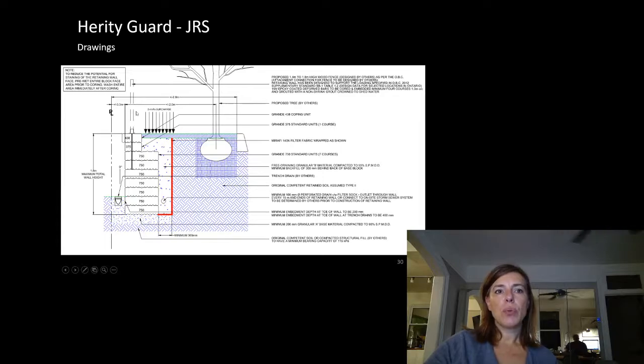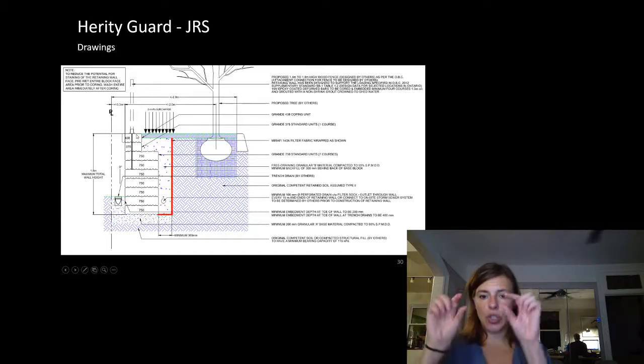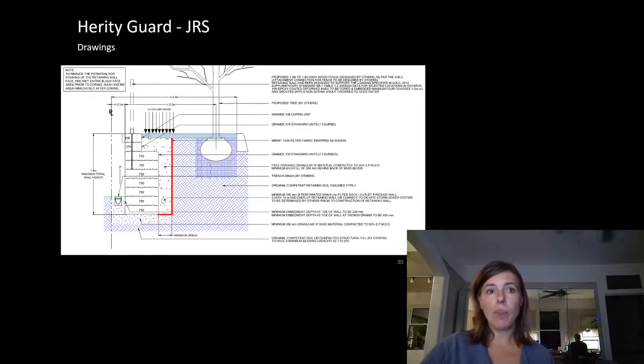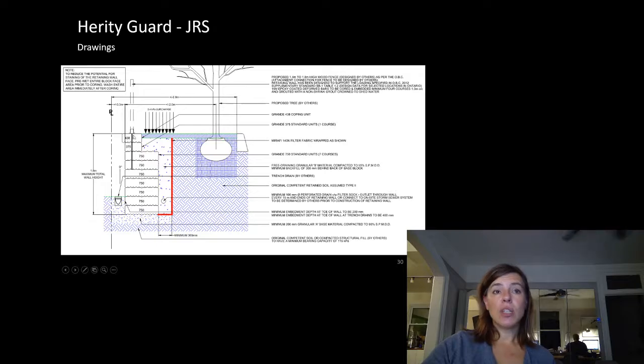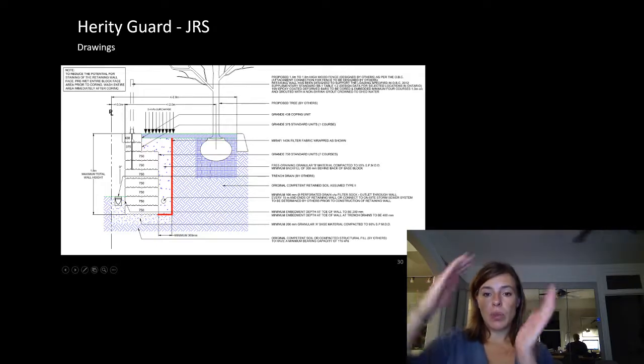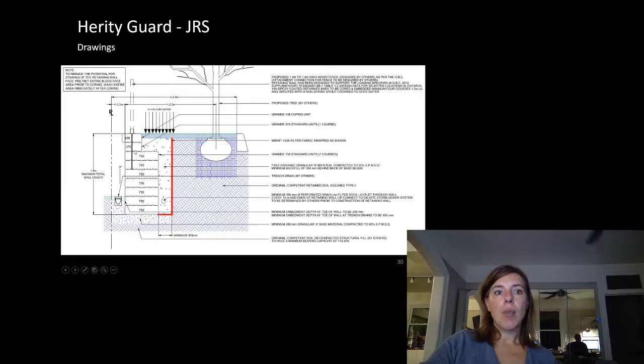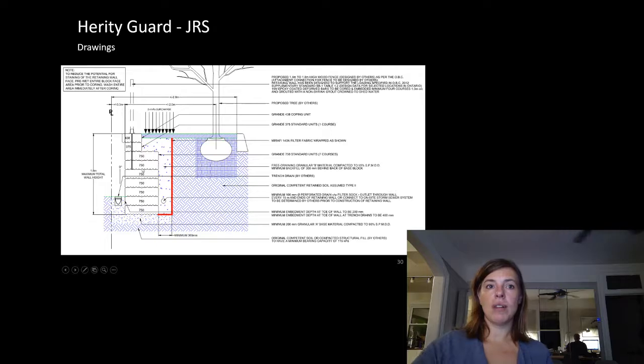It was an interesting process because we couldn't just Hilti into this one stone, because there's nothing connecting these stones to each other. As this tried to rotate, the couple that I would normally do into concrete, for example, which is just two anchors resolving that couple, would work. The fence would be securely fastened to this stone, but the stone would tip over. And even this stone would tip over. And even these three stones would tip over. We had to drill down to engage these four stones to not tip over.